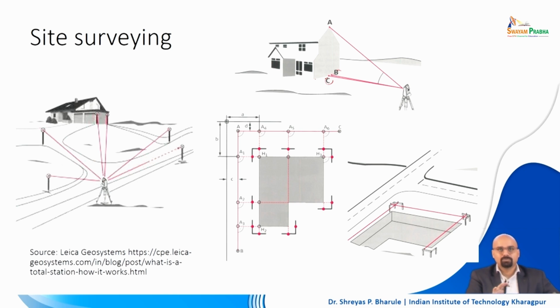So, that is how you do the survey, and you place that particular point in reference with the actual stationary building. A building won't move, right? Maybe trees might get cut down, billboards might move. So, it is always recommended that you identify one simple place where you will have a point of reference which will not move, which will be stationary for the rest of the time, till your building is being executed, till your construction is completed, right.